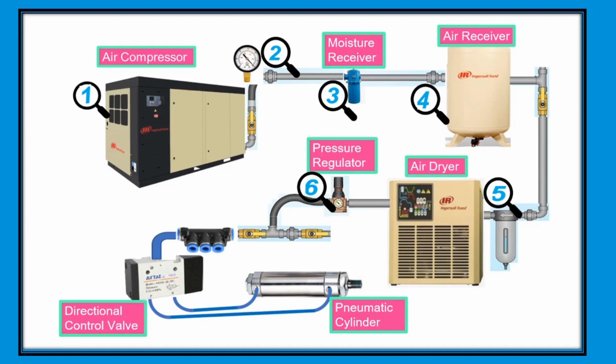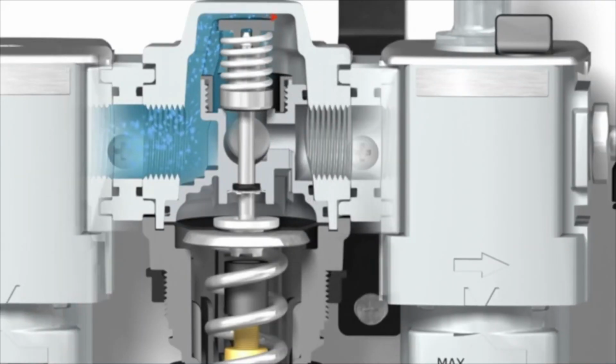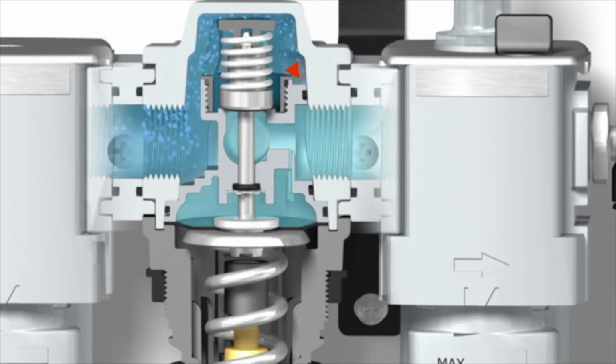Its volume reduces pressure fluctuations arising from the changes in load from the compressor switching. Any moisture left in the air from the compressor will condense out in the receiver, so outgoing air should be taken from the upper side of the receiver.